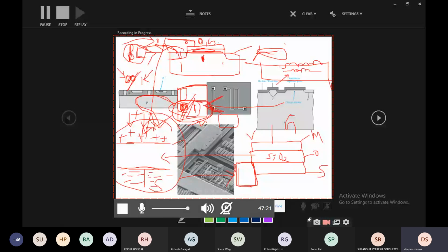And spiral patterns can be defined by photolithography. See, the spiral thing should come, right? Again, that can be done by photolithography by using the mask. In that mask, we should have the spiral pattern, right? So that spiral pattern can be imprinted on the chip using that mask. So by the process of photolithography, even fabrication of inductors onto the chip is possible nowadays. Photolithography followed by etching, correct? Just like we have the mask for rangolis, if you have seen in the markets, right? So mask for the rangolis, like we have mask for the inductors. Understood?